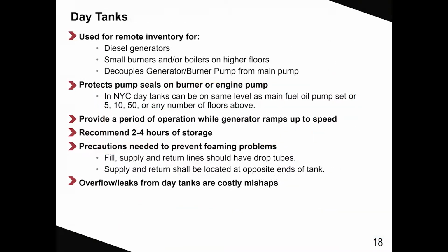Day tanks. Day tanks are used for emergency generators, boilers, and other fuel-burning devices. Used for remote limited supply at the fuel-burning device and decouples the appliance pump from the main transfer pump on the bottom floor. We recommend a 2 to 4 hour storage at the remote device.